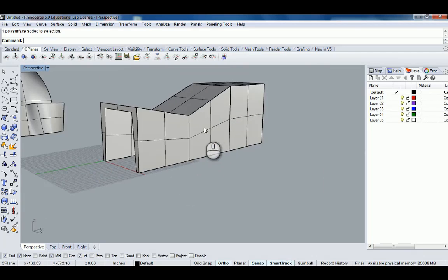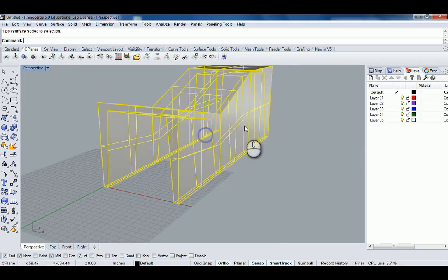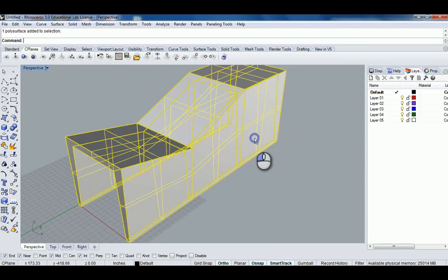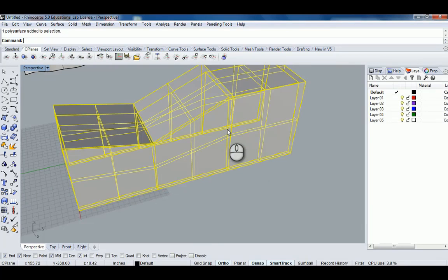We could also, given that this is a little bit inefficient of a surface edge here, in that it's 3 surfaces rather than 1, because they're all coplanar, simplify the poly surface. There's a couple different commands for this, but basically, because this is already all joined together, you can merge all faces. That's a command.